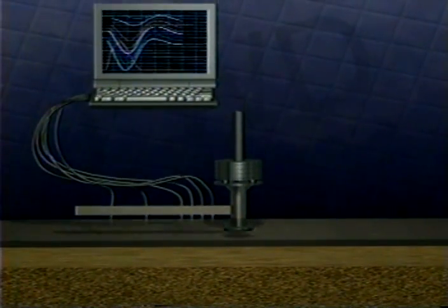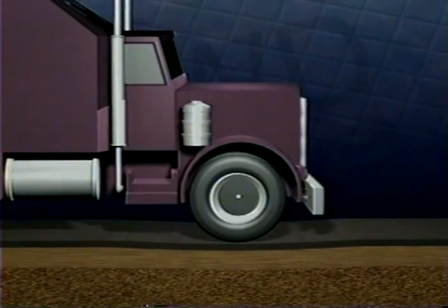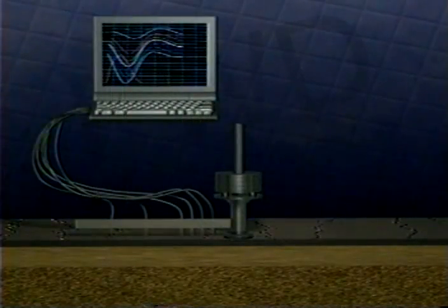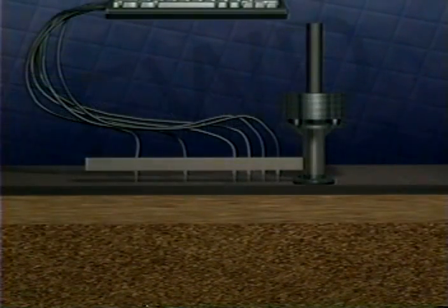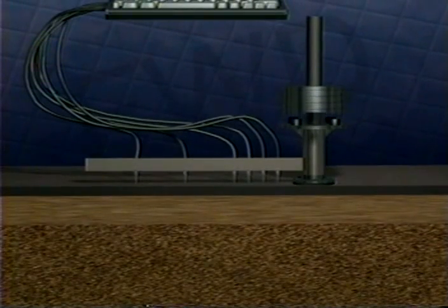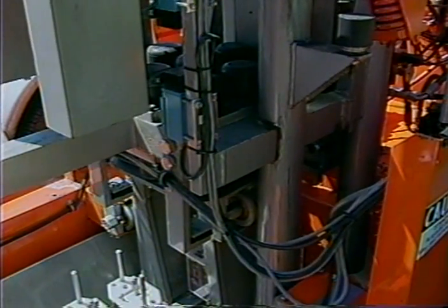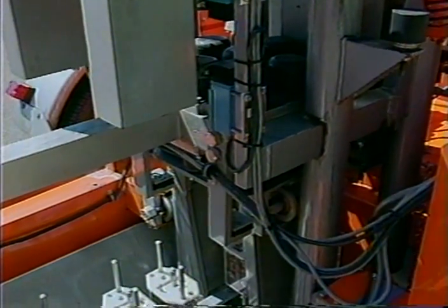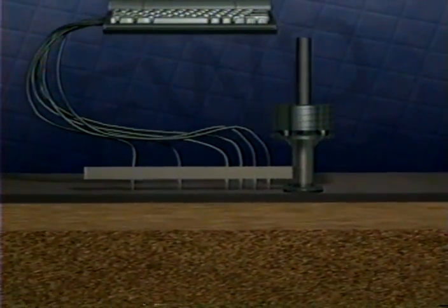When the FWD lowers its load plate and drops its weight, it's simulating the load that vehicles put on the pavement every day. That constant loading can be a major cause of pavement deterioration. The pavement responds to the FWD's load by bending downward, or as we say, the pavement deflects. If you stand near your FWD when it's working, you feel the deflection. It's not subtle. The FWD's sensors measure the deflection.